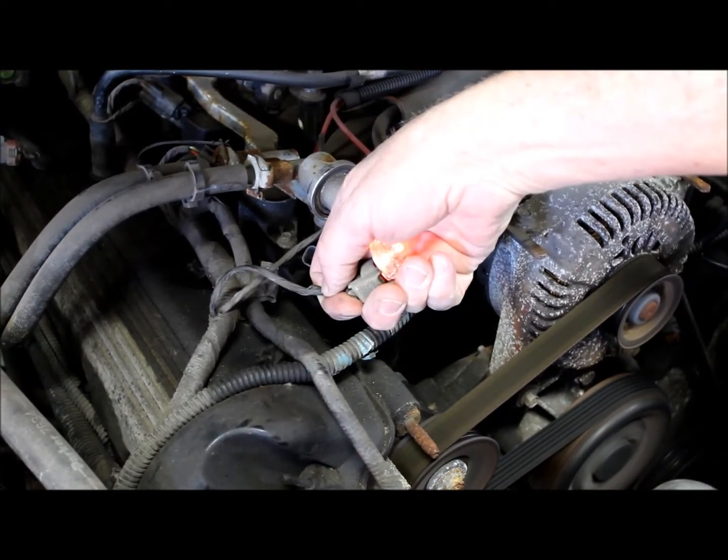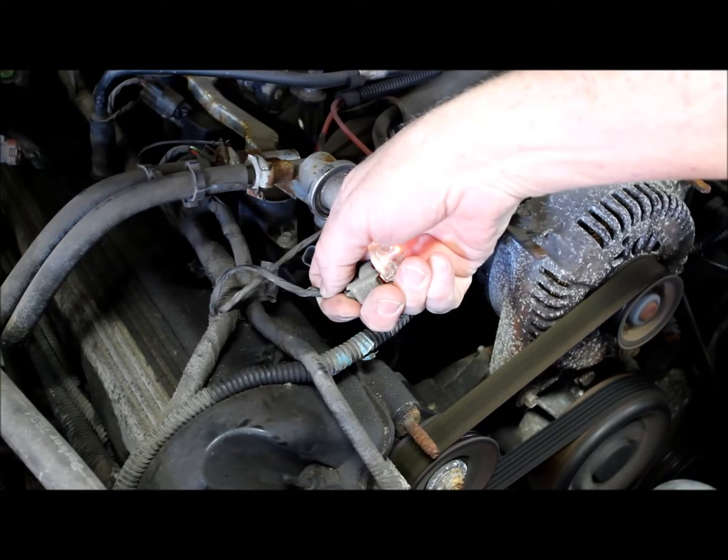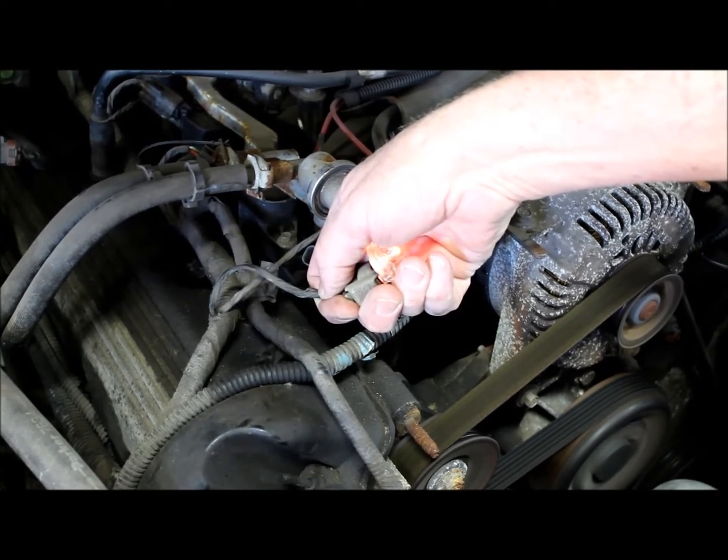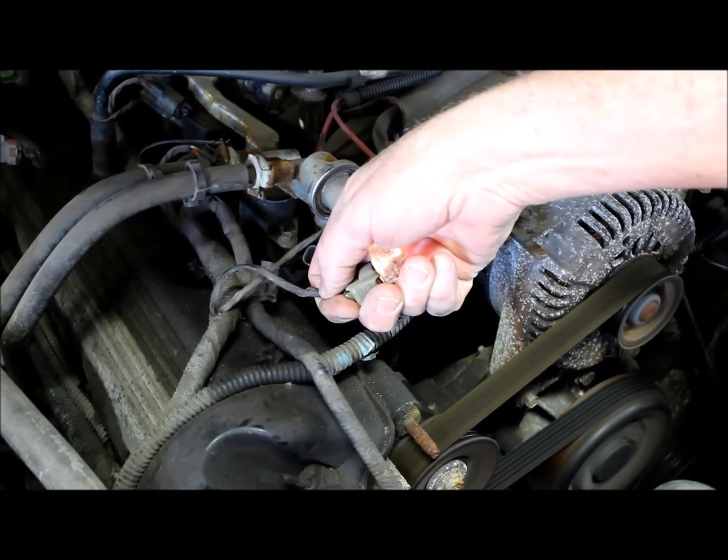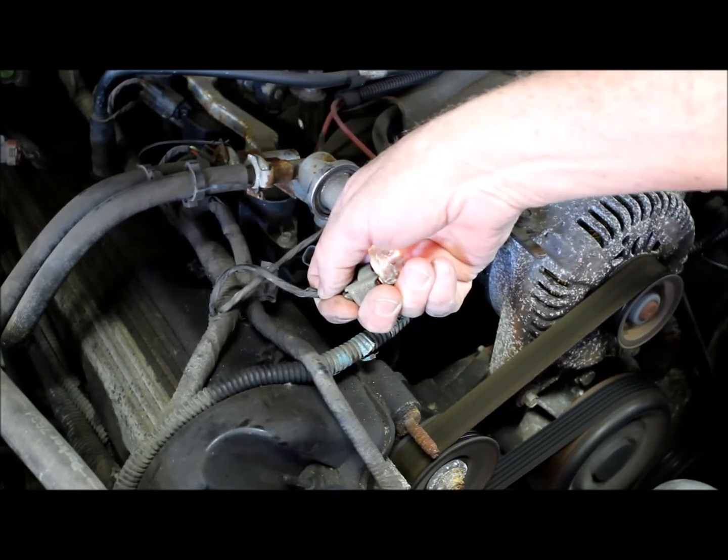You may be able to see that on the video, not sure if you can hear me over the engine, but it's flashing. Could be one pulse essentially for every time that injector needs to fire. So every intake stroke you're going to see another pulse.